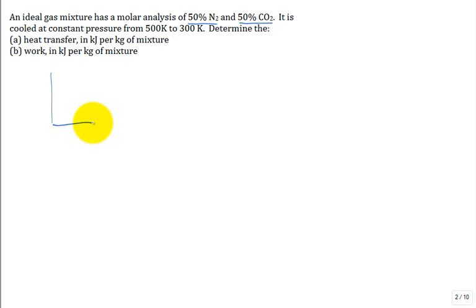So we basically put a piston of known weight, and that weight doesn't change, in a cylinder, so the piston dictates the pressure underneath in the trapped gas, and so the ideal gas mixture is what's trapped, and we then can subject that to some cooling, some heat transfer. And so that's how you would visualize it. I mean, we have a lot of piston cylinder diagrams in thermodynamics textbooks, so there you go, constant pressure.